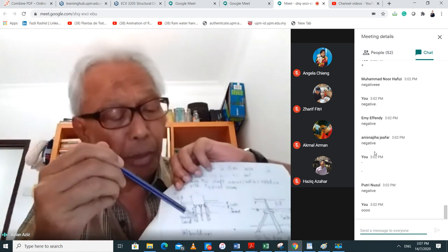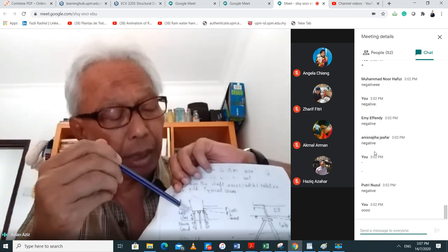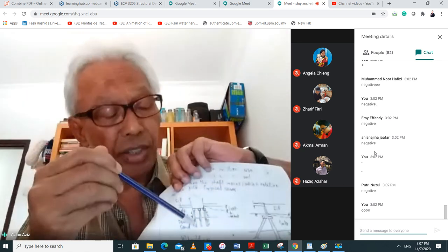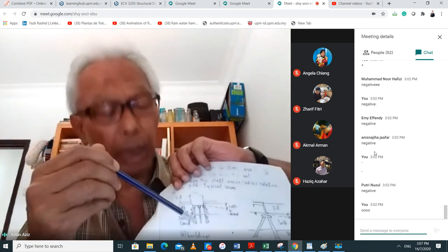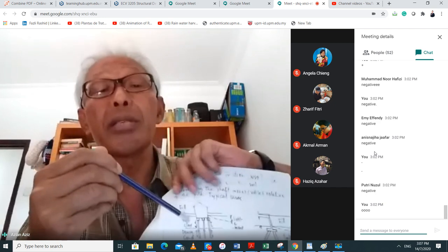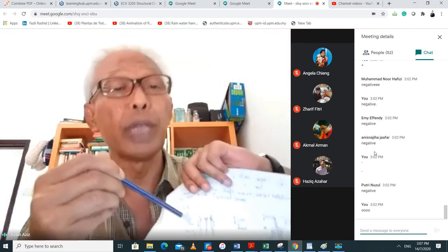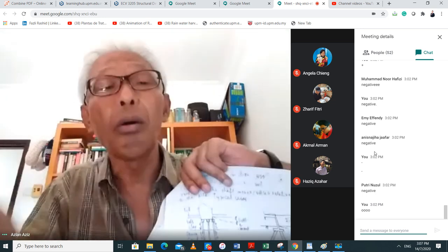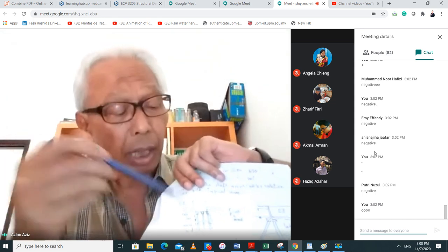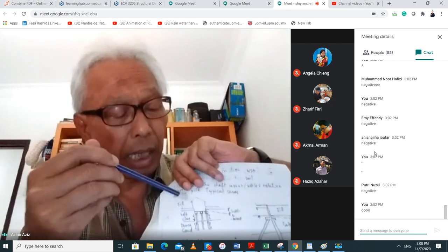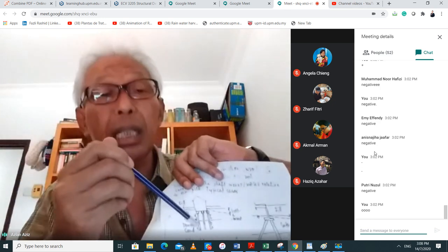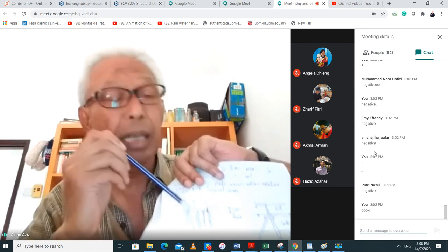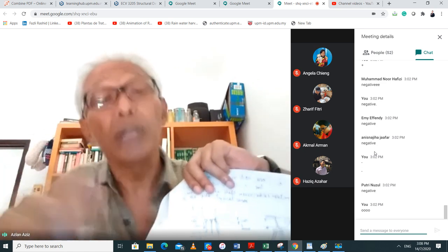So positive, fight against the load that you apply. Now, we have positive here, you have negative here. Say you have 10 units of load you're giving. This is from the dense sand, you get 8 units. And say from the stiff clay, 2 units. Okay? 8 plus 2, 10, fight against 10, cancel. Now, if it is negative, 10 going downward, you get 8 here, this minus 2, negative 2, 8 minus 2, you get 6. So it's lesser now.